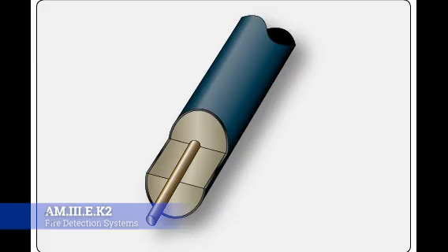Now that's all fine and well, but what makes it really powerful is that whenever it's in a loop, you can cut the thing in half and it'll still work. It'll still basically close an electrical circuit and set off all the fire alarms. The other big advantage is that it automatically resets. It will go off, and then as the fire is extinguished, it'll reset itself. And then the same thing, if that fire crops back up again in the same spot, heats it all back up again, it'll go off again until the fire is extinguished.